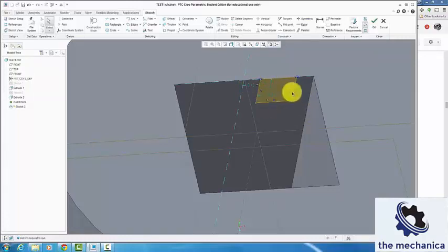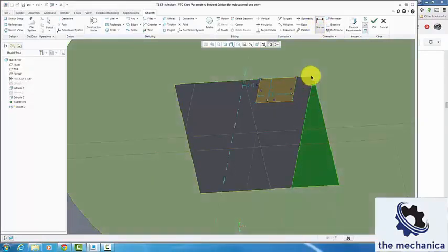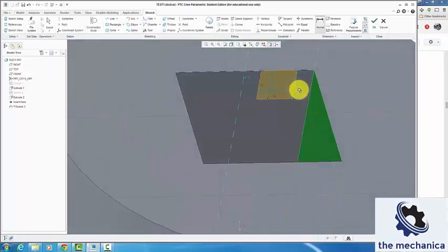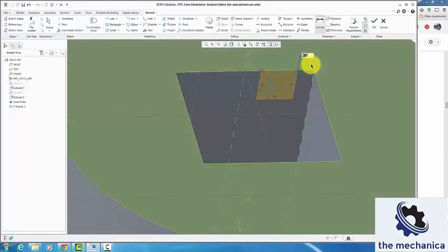So as I'm doing things, I can move things around. If I want to dimension this and I want it to be 1/8 of an inch from here to here, right now it's giving me 1/8 there. But if I go to normal dimension, if I pick that edge and that face, I'm not seeing anything. If you're used to using SolidWorks or Inventor or anything else, you're used to dragging the dimension around. But if I just middle click, it puts the dimension in.